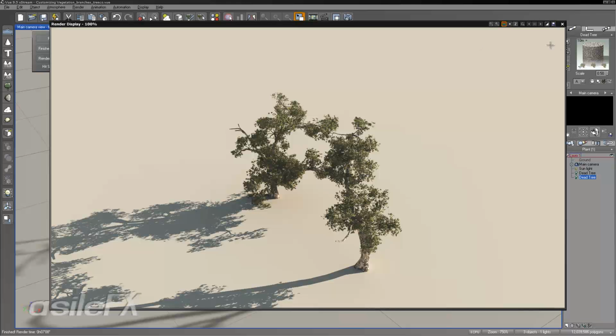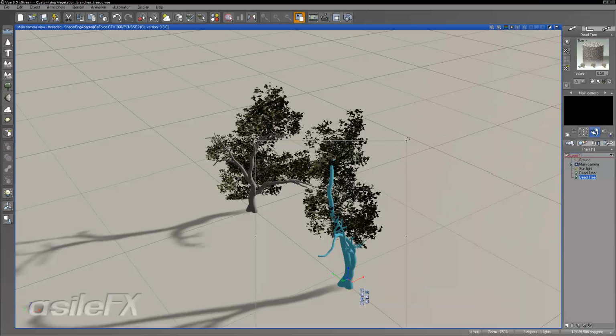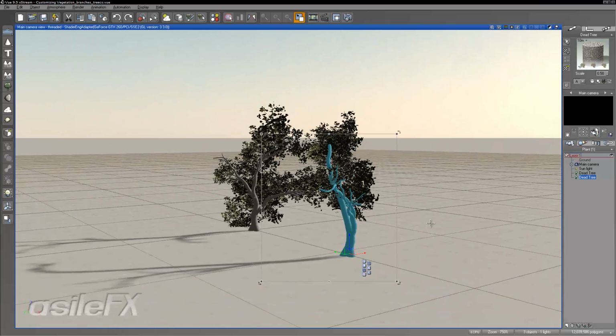For stills, though, it's definitely worth it. Animation, it probably wouldn't work very well, unless you optimize the lighting settings. Typically, you bake radiosity, though. And that would be an awful lot of work for this kind of a setup. But you can still get a pretty nice look, even by reducing the quality boost, which will definitely speed up the render a lot.